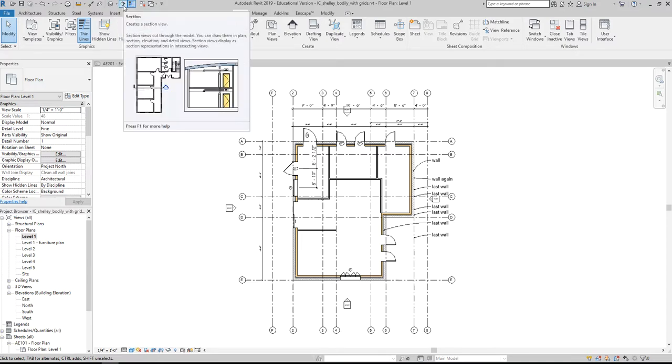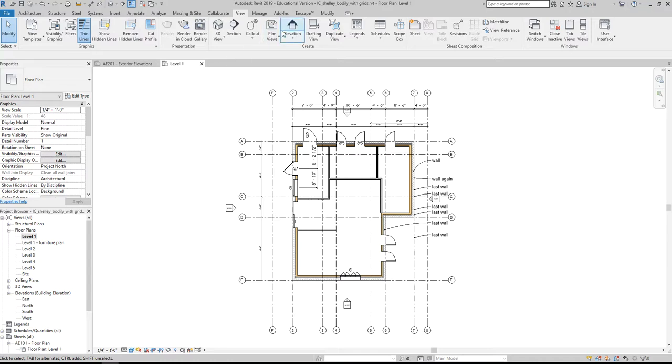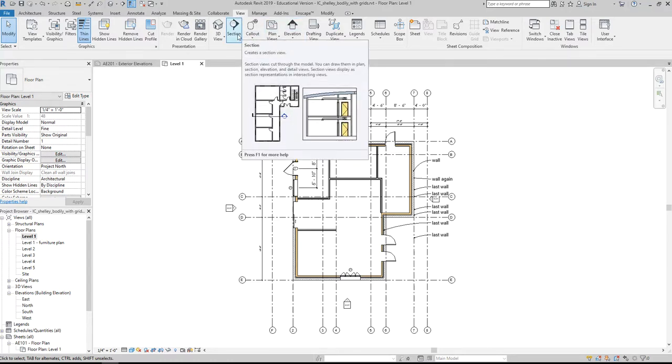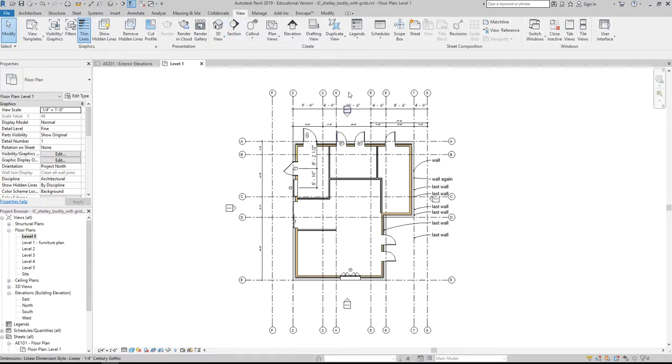All right. So a sectional view, which you may notice that we also have a sectional tool up here in the quick access toolbar. It creates a building section, okay, which is a vertical cut of a building. So a floor plan cuts the top of the building off and you view downward into the building. And a section is if you take a project and you cut it vertically and open it on a hinge. You can view the construction vertically of the project, okay?